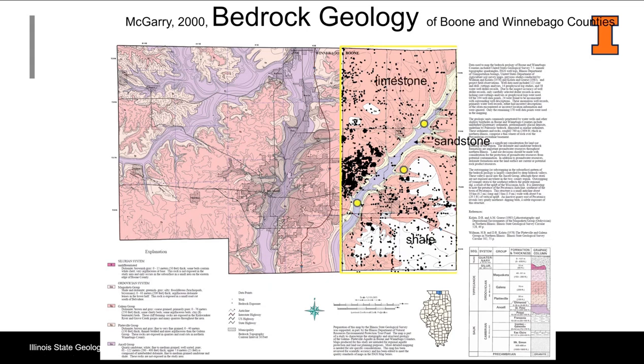So in the last few years, we've been using some other funds to map in Boone County. We've drilled 3 of our own holes. 2 of those holes got down into the bottom of the valley. One of them was on the flank of the valley. And unfortunately, drilling is not a perfect science. We drilled both of these holes that were supposed to be right in the middle of the valley, and they were deep as heck, but we couldn't get enough recovery in samples to really understand what that bedrock material was. It was very disappointing. We tried our best. We're going to try again. But we know those are very good control borings on depth of the bedrock valley.